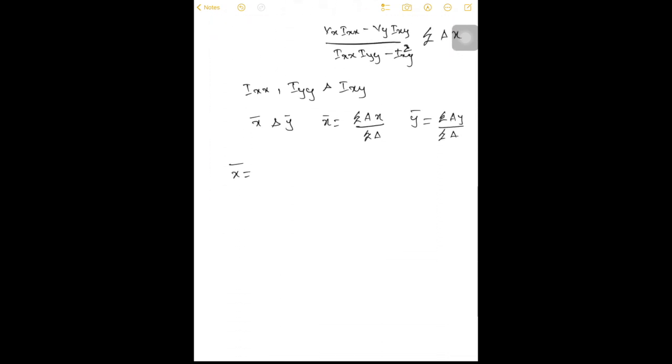So I can write: the area of boom A is 1 and it lies in the reference plane, so distance 0, plus the area of boom B is 1 into distance 0, plus the area of C, 0.5, which is 16 centimeter away from the reference line, the same way for D, 0.5, the distance is 16, divided by the area of boom A, B, C plus D. When you resolve this, you will get 16 divided by 3, which is 5.33 centimeter.